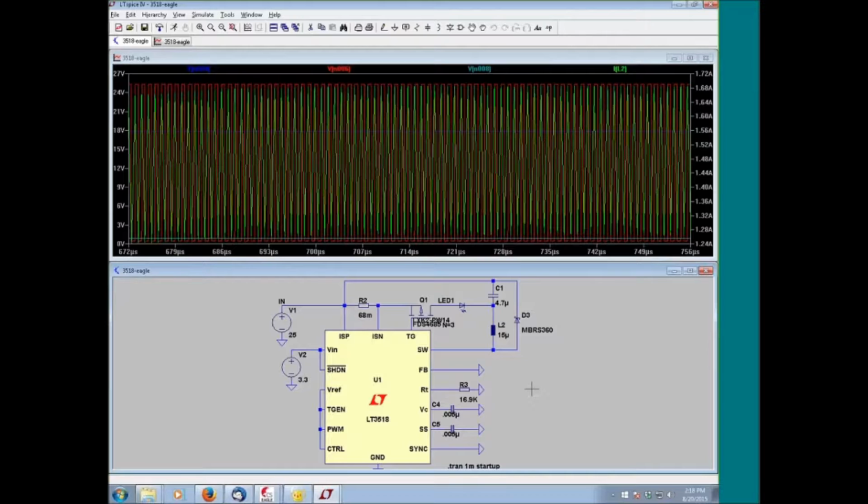Sometimes input bias currents are difficult to model, the input impedance, because it's often not purely resistive, but rather reactive in some way. Slew rate is also difficult to model, and so on and so forth. So depending on your model, certain effects may not be observed, and those may be critical to your application.